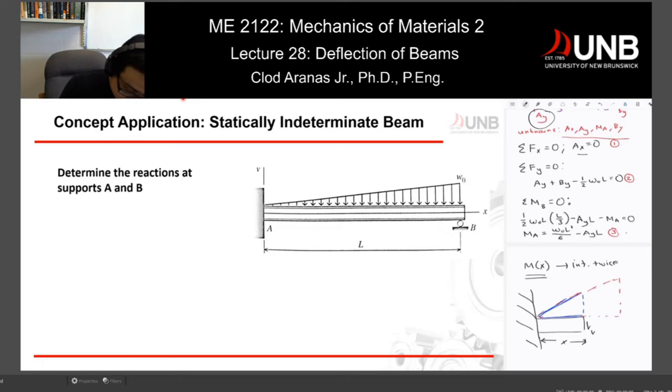I'll assume my shear force at the end of my beam, which is V, is not 0 because it's in between A and B. And I would also have a moment at the end, which is M. All of those are just assumptions for now, all the directions. And again, once you have numerical values, it will just self-correct once you plug in the numbers. Now, you have those assumed directions right now. What else do you know? Now, I know that at this point here, this is the purple one. So this is W naught, and this is L right here.